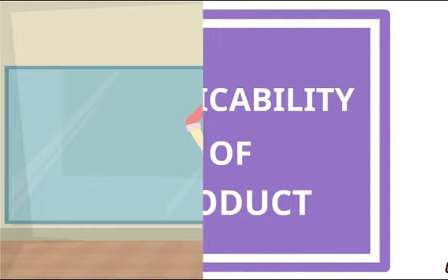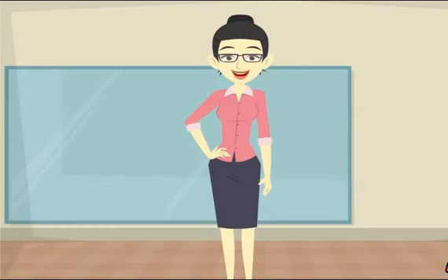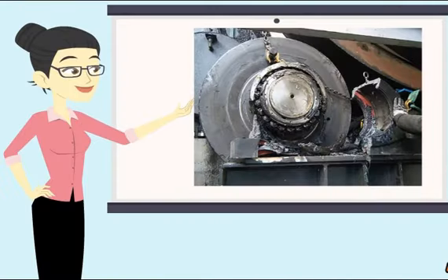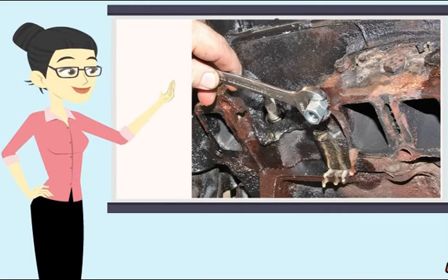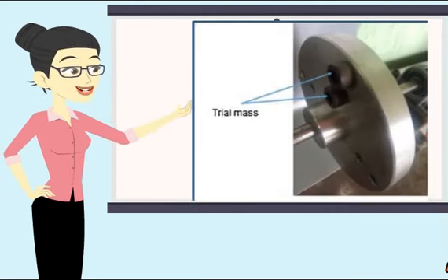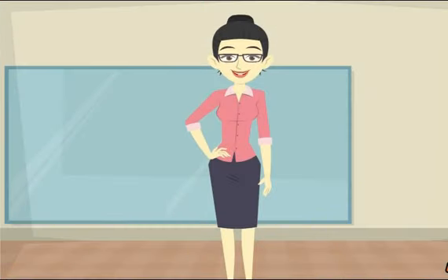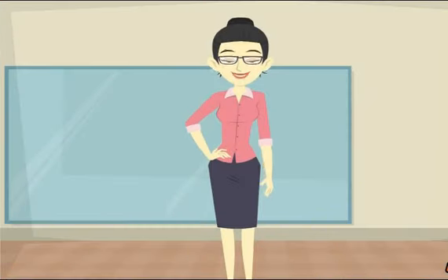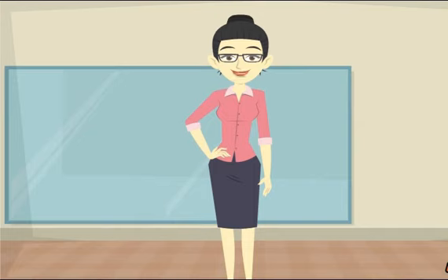Now, applicability of the product. The product that we have designed is applicable where the vibrating machine is showing symptoms due to defects in bearings, looseness of fixtures and fittings in the system chassis, or any uneven load on a shaft, for which if not predicted in time can result in breakdown of the machine leading to disaster.